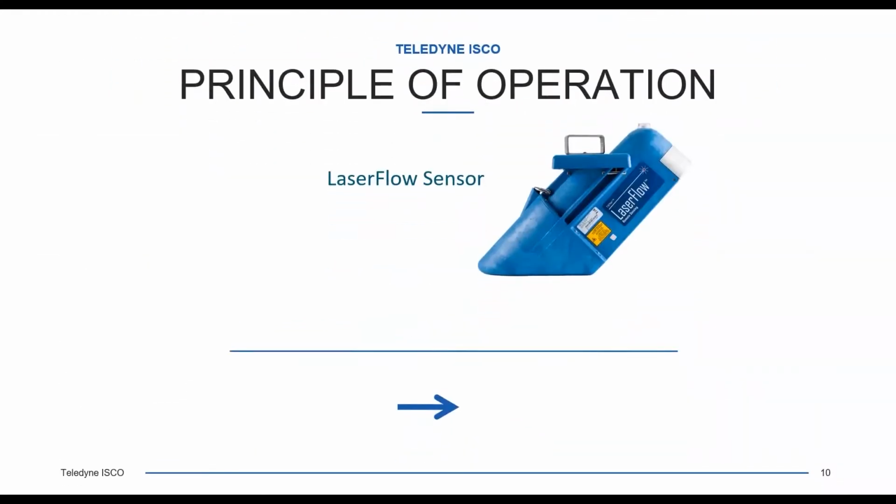How does this thing work? It has an ultrasonic sensor that's mounted in the back, and it has a 10-foot range. So it can be 10 feet above the minimal flow. Sometimes people have them in bigger pipes than 10 foot, but the flow cannot be greater than 10 feet away from the sensor. We also designed this to be what we would call a zero deadband sensor. What I mean by that is every ultrasonic will typically have about a 1 foot deadband, including ours. So what we did is we put that at the back of the sensor.